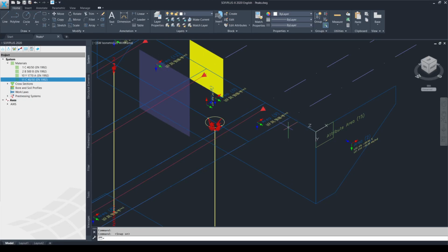The way how you can avoid this is exactly the same as what I just presented for the wing wall, namely to create an attribute area along the edge over a certain height where the quad elements are undesignable. Having said that, basically that's all that I can offer or recommend to avoid these peak values in the bending moment diagrams at the problematic locations of this type of bridges.